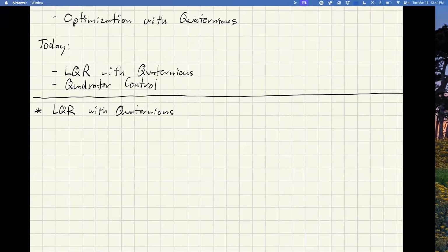Okay, so back to what somebody asked, I think you just asked a little bit ago. We talked about this rank deficiency problem. If you're looking at a linear system like AX plus BU, another version of that rank deficiency story is that the system in 4D is always uncontrollable. So if you try to do LQR on that 4x4 system, it will never converge. Riccati will not converge because it's an uncontrollable linear system, because by definition, you can't control in the length direction, right? So that's also part of the story. Basically, all the stuff breaks and you have to do some tricks.